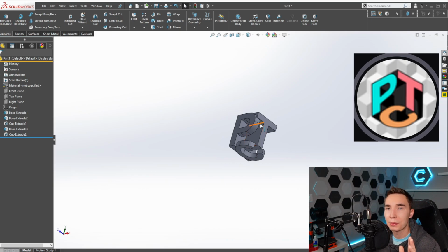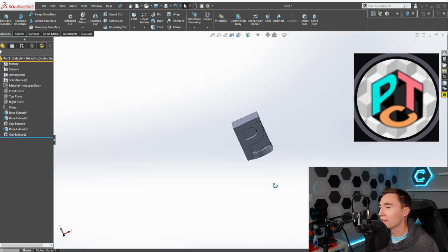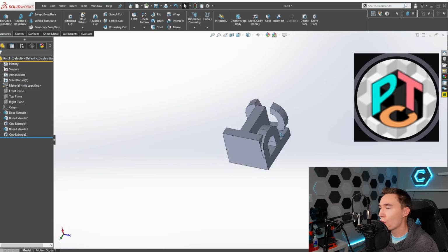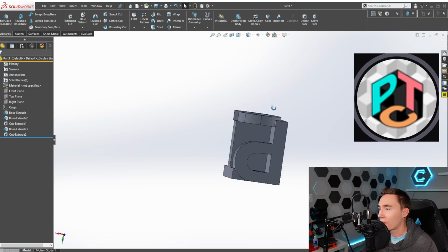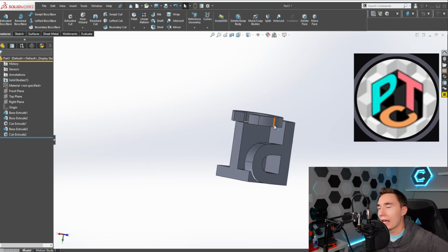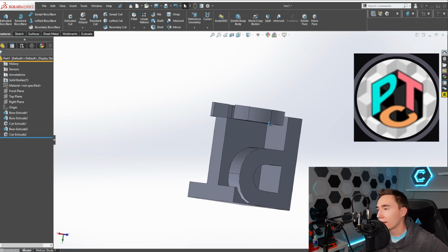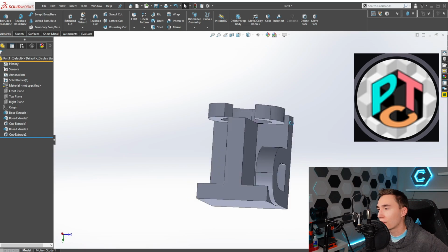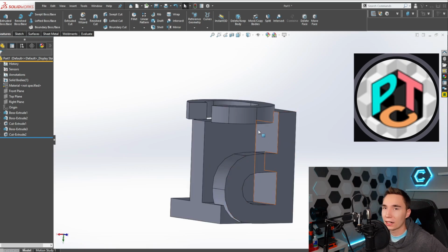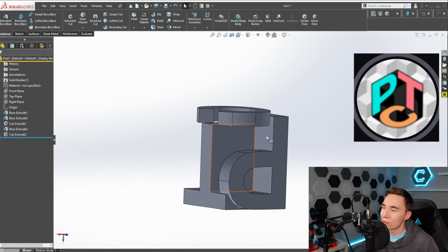So, I'm gonna be honest with you guys. I tried printing this before I made this video. I did make this model before I make these videos. I do it all the time because I mess up a lot. So I actually tried printing this in this orientation, like so, leaving the C as part of the whole deal, and it didn't work too well. Just adding the support material in here and then trying to take it out and have it clean didn't work that good. So we're actually going to split this into 2 parts.